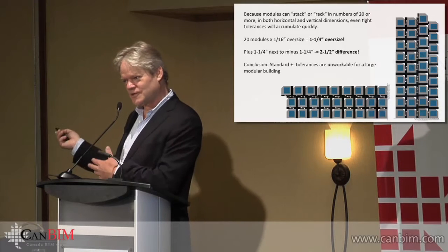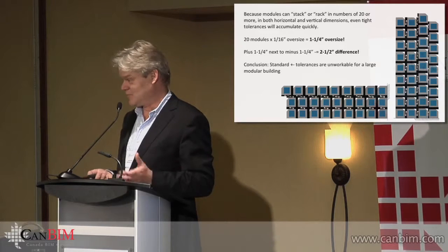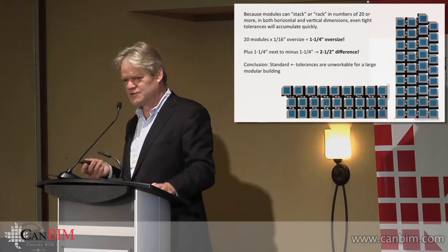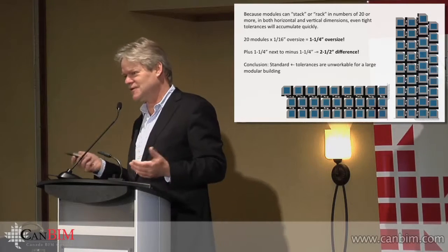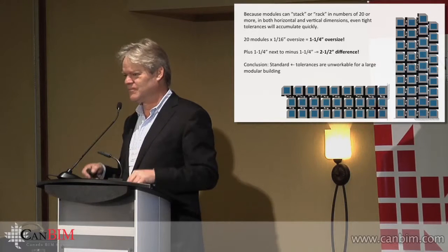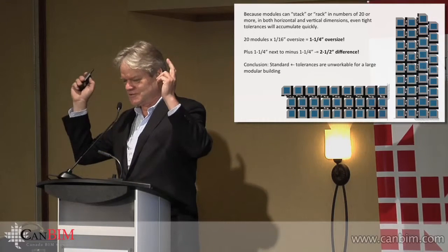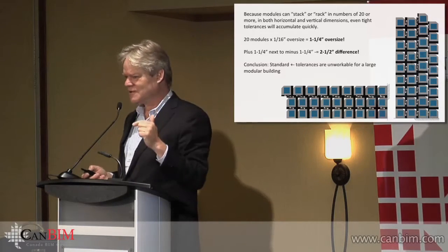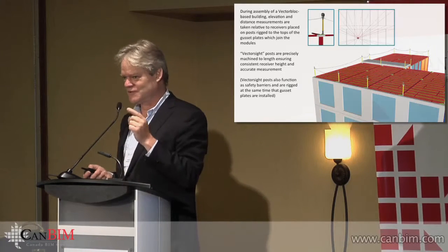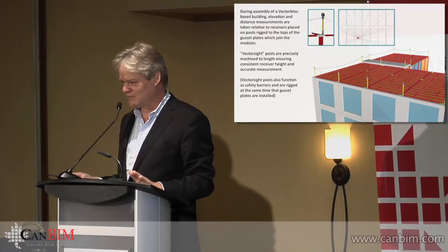But if you're trying to prefabricate modules in a plant and erect them in the field, you really can't do that. A lot of your opportunities for adjustment are lost. So this plus-minus tolerance envelope idea doesn't work for modular construction. You have to have a plus 0, minus something tolerance envelope. So you think of that jig: if you're going to make a module that's 10 feet wide by 10 feet high, you will actually always set everything at 9 foot 11 and 15/16 by 9 foot 11 and 15/16, so that for sure nothing is going to get too high.